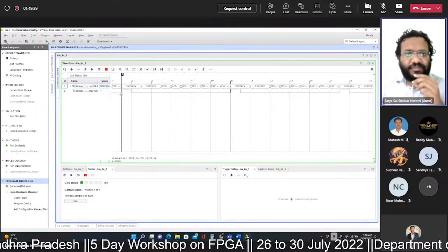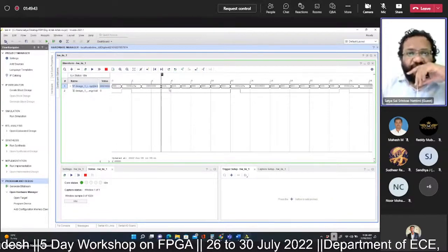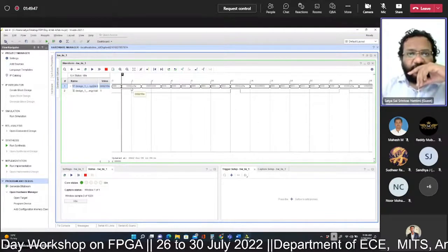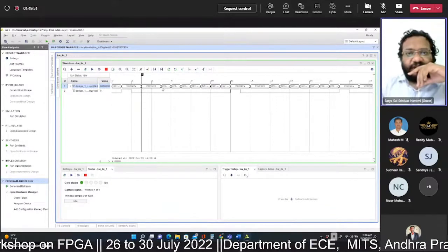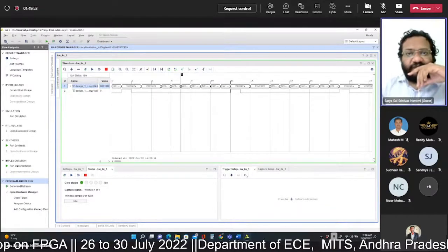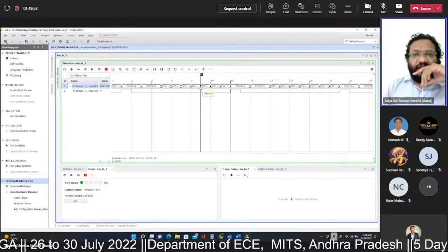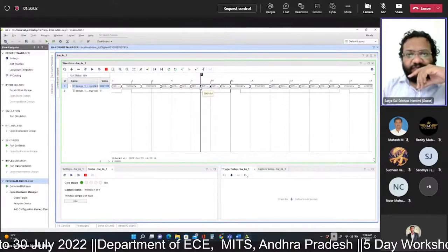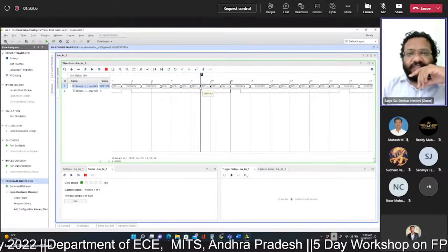Whenever the energy value is high, we are getting a valid signal. During the computation, this energy value comes directly from the energy register, which is continuously updated at every clock cycle on arrival of a new sample. That means we are accumulating the result: energy equals the existing value plus the square of the current sample.